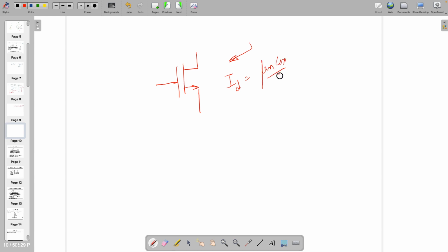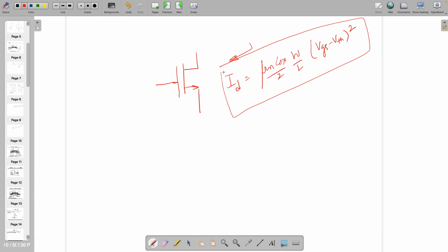By the way, the equation that is written is not fully true. It's only for the transistor when it's in the saturation mode of operation, right? For other modes of operation, this is changing. So then this equation does not hold, by the way. In all different regions, this equation is different. For triode, it's different. Even in cutoff, it's different. So all equations are different. So when you are simulating this for a given region, then you need these parameters. Understand?